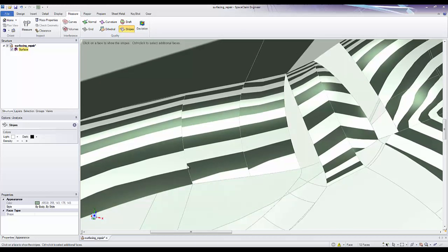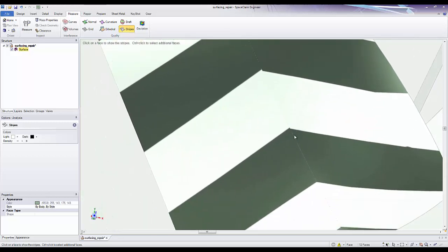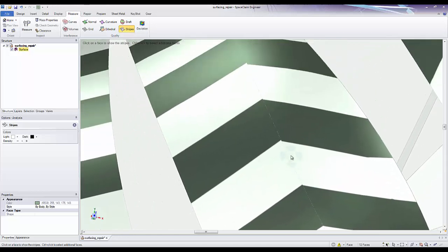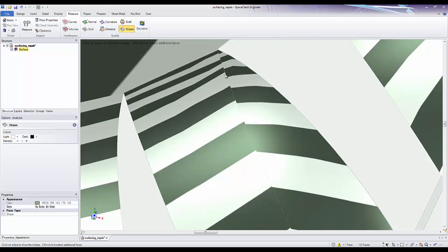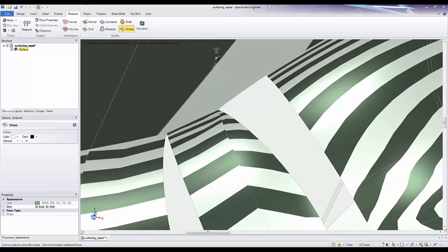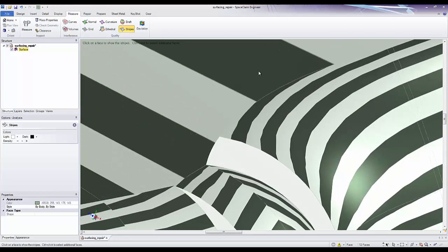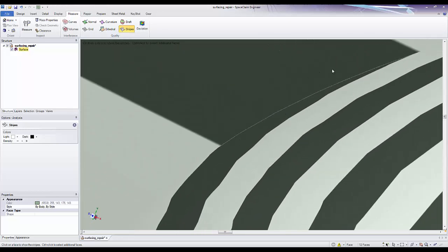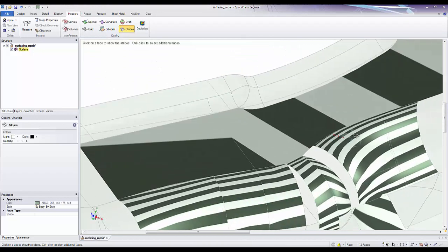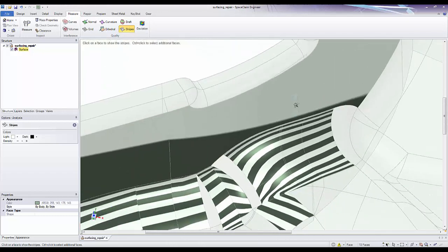And what that stagger indicates is that this face and the face next to it are not actually tangent. Over here, they're close to tangent, but there is a little step in between them. You can see it gets worse and worse. So we need the two stripes on either side of the edge to meet up to show that they're actually tangent. And depending on the view orientation we're in here, we actually see we have a nice tangency to the faces above, and on this side here, we do have some nice clean tangency.